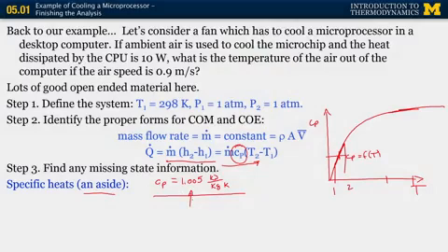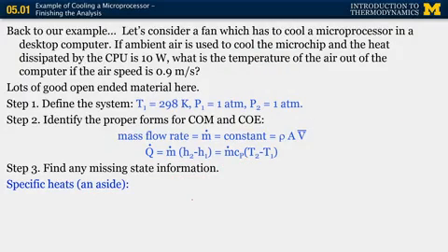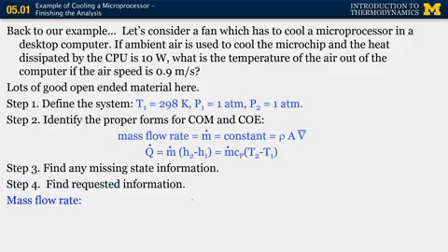Okay, so again, that was a little bit of an aside. So let's finish it up. Let's wrap up the rest of our analysis here. So we need to find the mass flow rate. If you crank through and did the rest of that calculation, we found the density of air. Let's take that density, plug it into this expression. Let's assume, again, the area is 1 centimeter by 2 centimeters, and that's an approximation. We're given the wind speed, so we plug all those in, and we get a mass flow rate that's equal to 2.13 times 10 to the minus 4 kilograms per second.